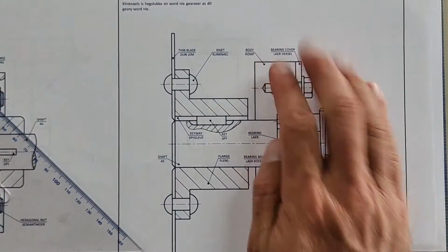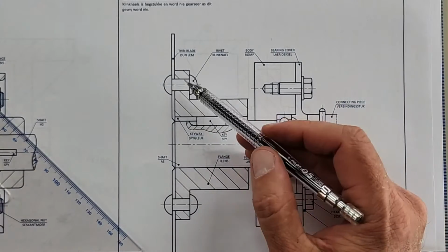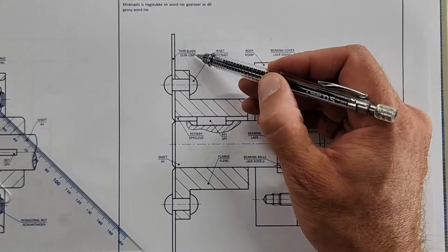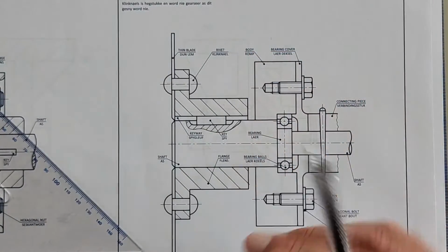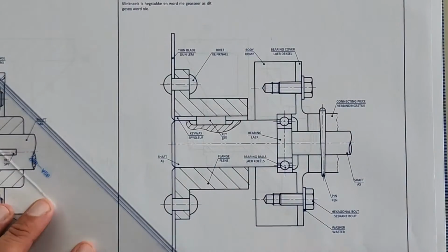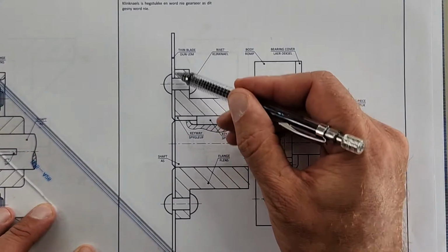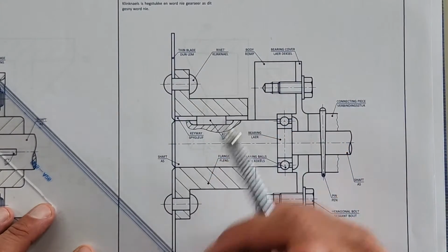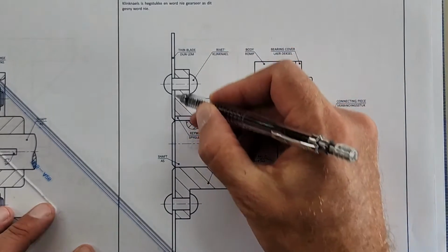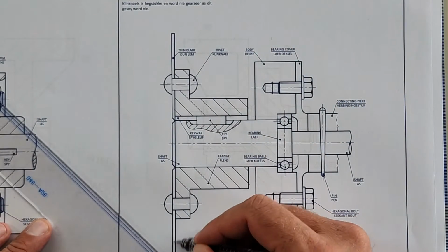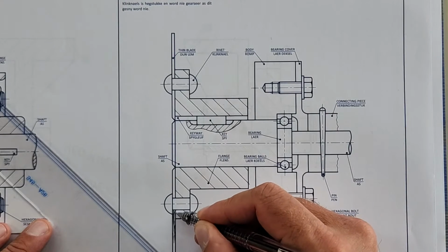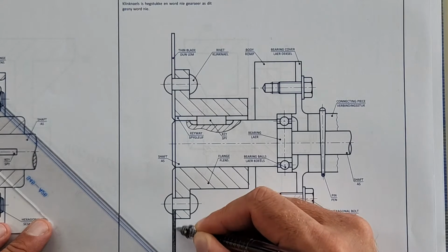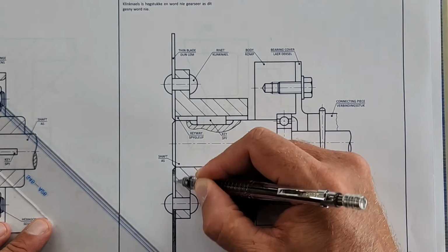Alright, so let's forget about this part, just concentrate on this part. We have our rivets. We're not going to hatch it. But then they have here a thin blade, a thin blade that runs here. Alright, practically to try and hatch this, it's going to be very difficult to do it accurately. It's a very thin component, so my hatching is going to be very close to each other. So the rule here, when I have a thin component like this, is I color it in. Alright, so just freehand coloring it in. You're going to darken it. Try and do it neatly so that you don't have any white parts in it. But you can just color it.